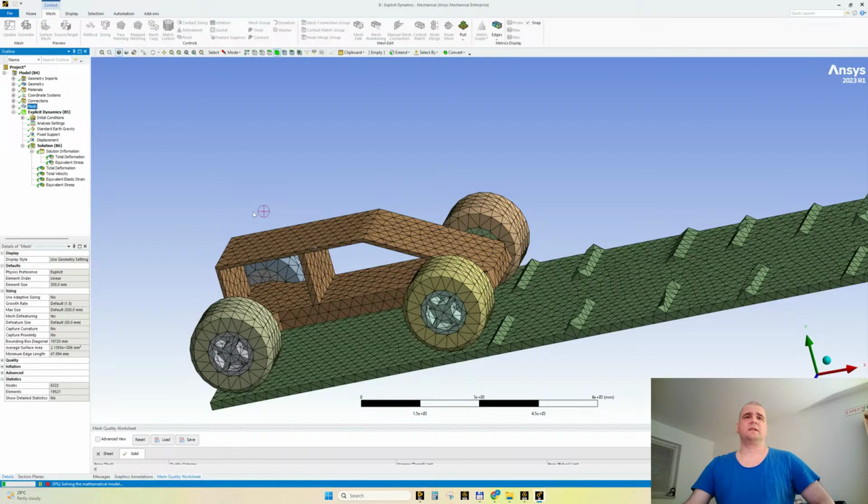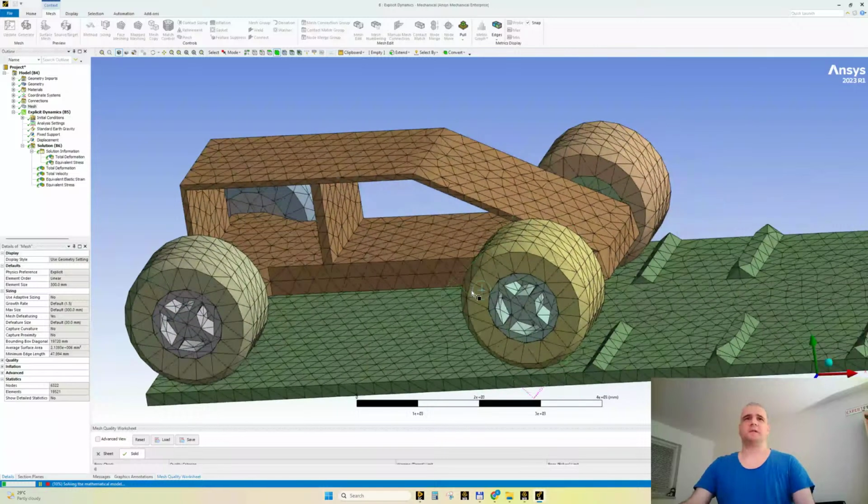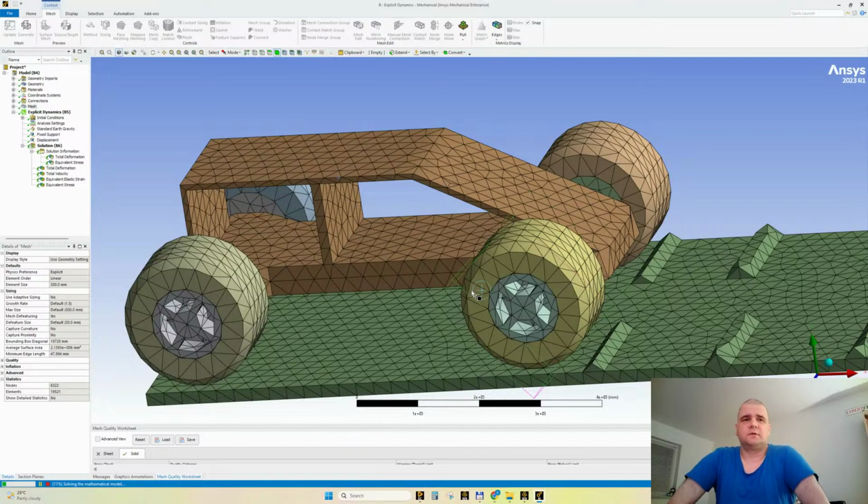So just let me tell you, working for an automotive OEM right now, we do have specific standards for meshing. In our team, in our research, we should verify the mesh quality, and we should make some convergence studies with the meshing, depending also on the parts.